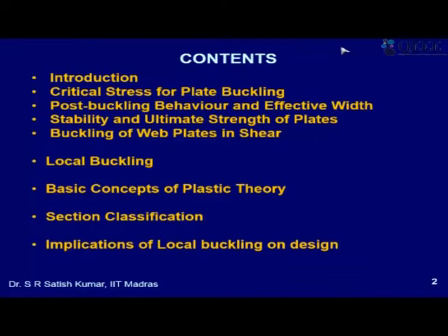So the contents for the first presentation are like this. That is introduction and critical stress for plate buckling. Then post-buckling behavior and effective width. I just want to give some introduction to post-buckling behavior, and after that we will proceed to stability of the plates, and we'll have a quick look at buckling of web plates in shear. Web plate buckling in shear is important for plate girders, but we are not going to go into plate girders today. But we'll just have a look at that, and then we'll proceed to local buckling.